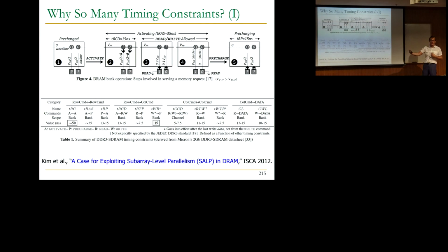The other option is to have an asynchronous interface and basically do away with all of these timing constraints. The memory controller sends a command or whatever request. Maybe the interface is at a higher level, or a function. It basically requests an acknowledgement from DRAM when it's done. Right? Or maybe it can keep sending commands, and if the DRAM cannot handle them, DRAM sends back a message saying, oh, sorry, I cannot handle them, so I'm going to negative acknowledge you. Right? This is called a NACK.